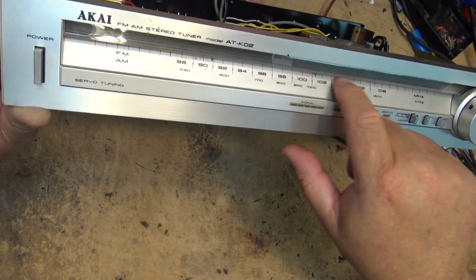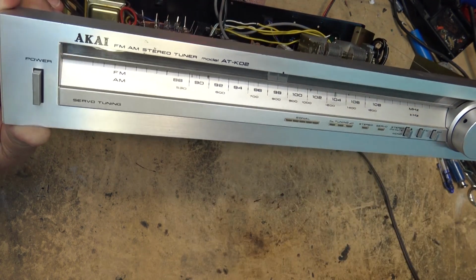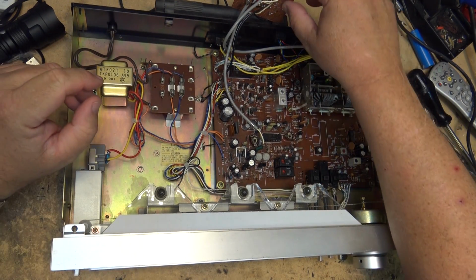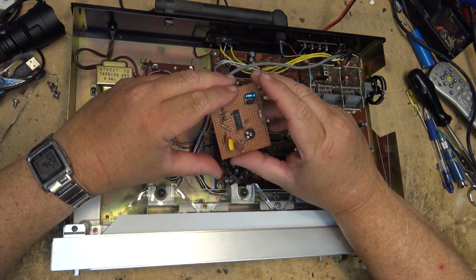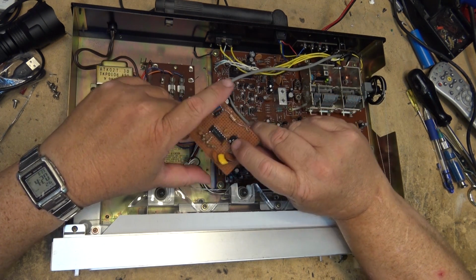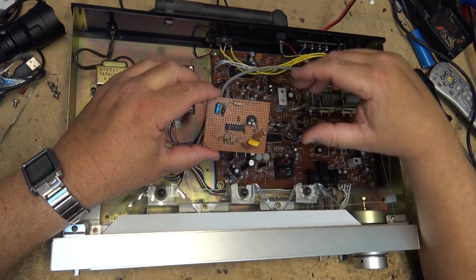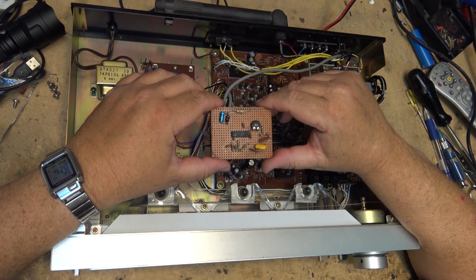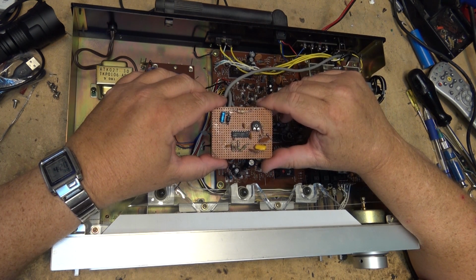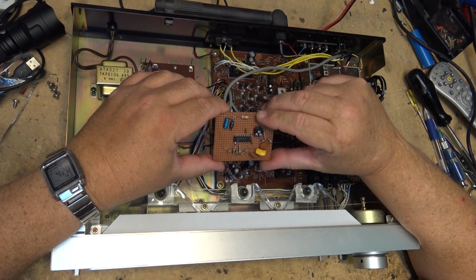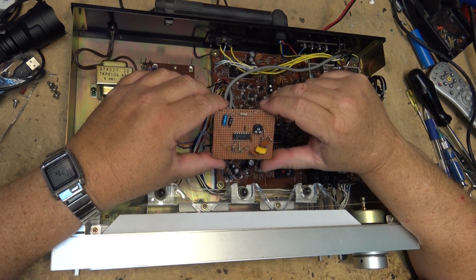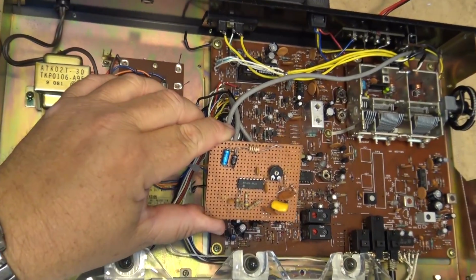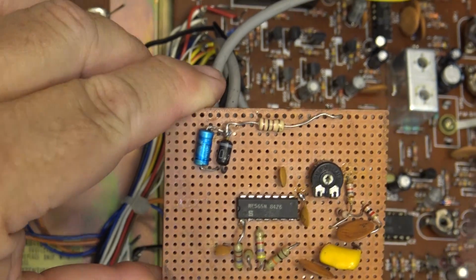These were all the stations that had SCA feeds on them, so I could just tune it in. At one point I had an external pot on this thing that I could use to tune to the one I wanted. This is the trimmer now to set the frequency, but this is the little board that I came up with when I was a teenager, I guess. I don't even know where I got the circuit from. I may have looked it up somewhere. Anyways, you can see this is my crude attempt at a regulator, just a resistor with a Zener diode, but it's based on an NE565.